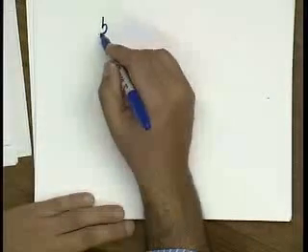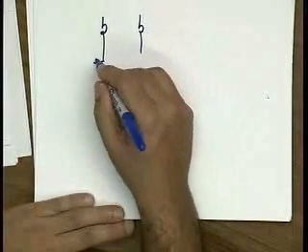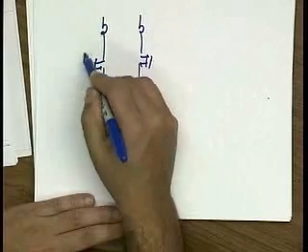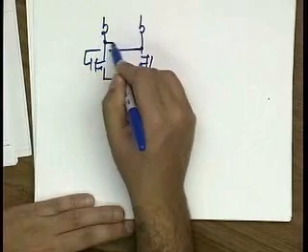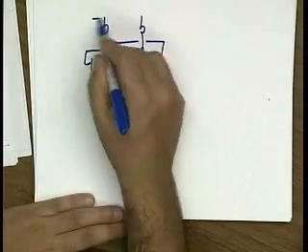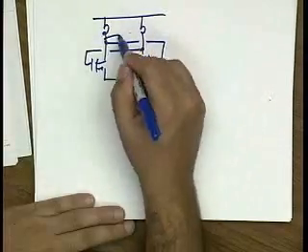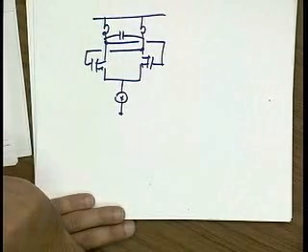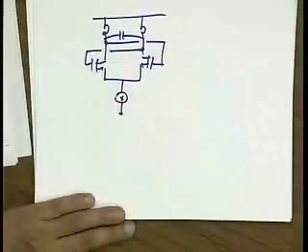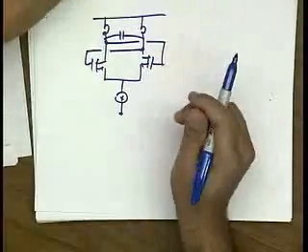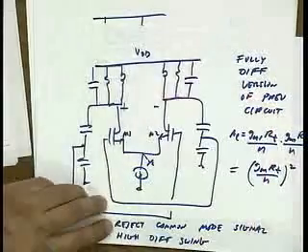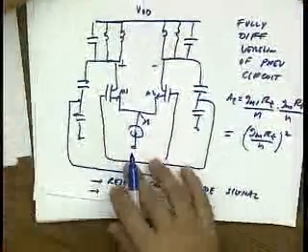So the idea is now have my inductors, and I can just take these signals directly and connect them, and I would also connect a capacitor across here to resonate with this inductor. And basically here, to make an LC tank, I forgot to put in my caps. So let me step back and put in my caps.